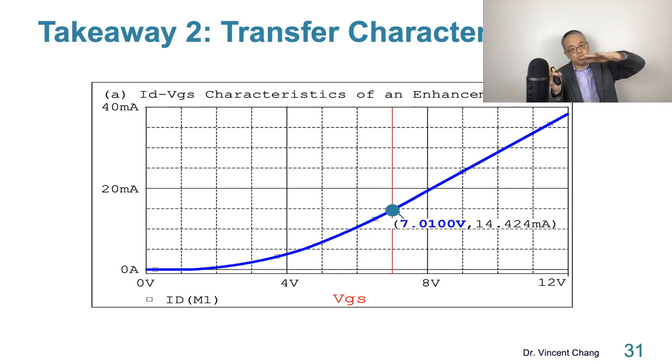You're going to see the square law. But when you keep increasing VGS, the status quo changed. The situation is changed. The device is going to leave saturation into the triode region. And the equation is going to follow the linear equation between ID and VGS when VDS, in the simulation case, is fixed. All right, this is the tricky part.